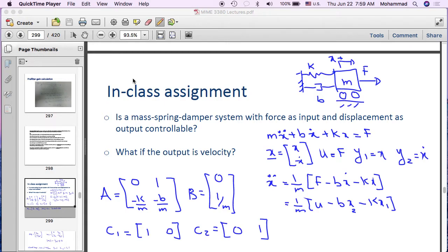Okay, let's pick up where we left off in the last class. If you recall, we've started working more and more on designing state feedback control, which is also known as pole placement. So if a system is controllable, that means we can place its open loop or relocate its open loop eigenvalues or poles anywhere on the complex plane we want.